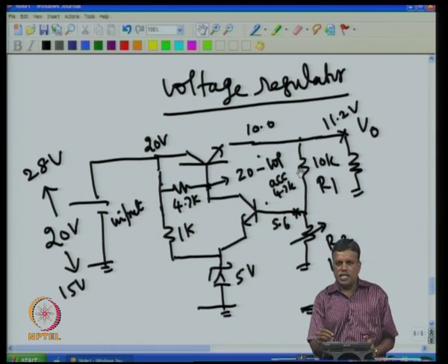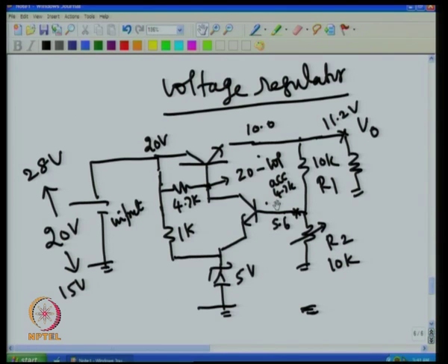It was extensively used in earlier days, and in fact even today we use this regulator where the regulation requirement is not very tight. Okay. So, we have seen transistor usage, and also how the op amp was born from the transistor, and what the drawbacks of the transistor were. The drawbacks of the transistor were the voltage drift and the voltage change due to supply voltage variation. These two are eliminated by using the operational amplifier. Then also I have shown you this time how to use the transistor as a switch and how to use the transistor as a voltage regulator.